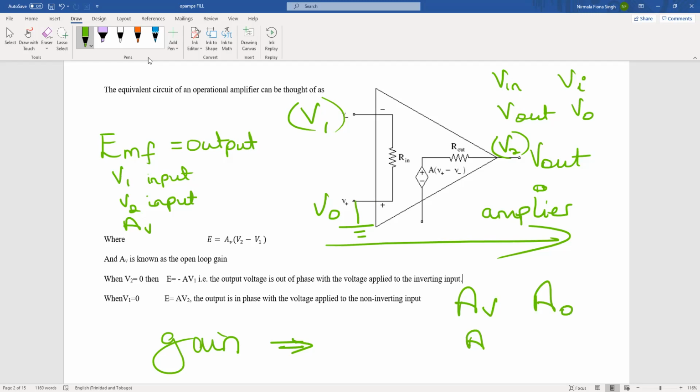Basically, gain is how much your signal increased by. The English language will tell us what gain is. And here, gain is simply telling us how much our voltage increased compared to our input voltage. So gain will be our V out divided by our V in. All right, that's simply down to plain simple language. Gain is your comparison or your ratio of your output voltage to your input voltage. And we have different types of gains to look at. They're not always just plain V out over V in. You're going to have some equations to look at.